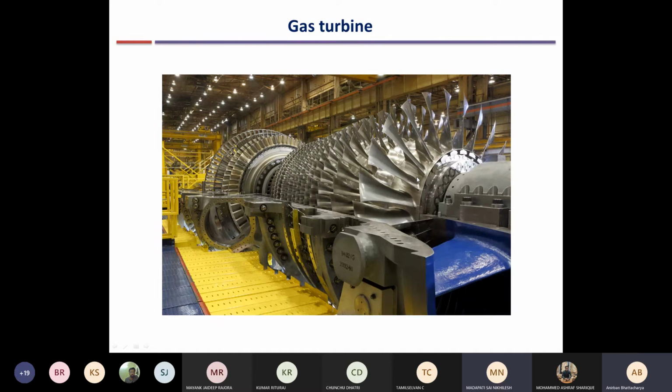So what happens in a compressor? The flow velocity is, so ignore the flow velocity. Okay, what happens when the flow is going from one side to the other side? Pressure is increasing or decreasing? Overall, pressure is increasing. Okay, and the flow has to go against the increasing pressure. So against adverse pressure gradient. Typically, when we consider normal flow, it happens from high pressure to low pressure, right? In the compressor, the flow is going against the pressure gradient. It is going from the side of low pressure to the side of high pressure.